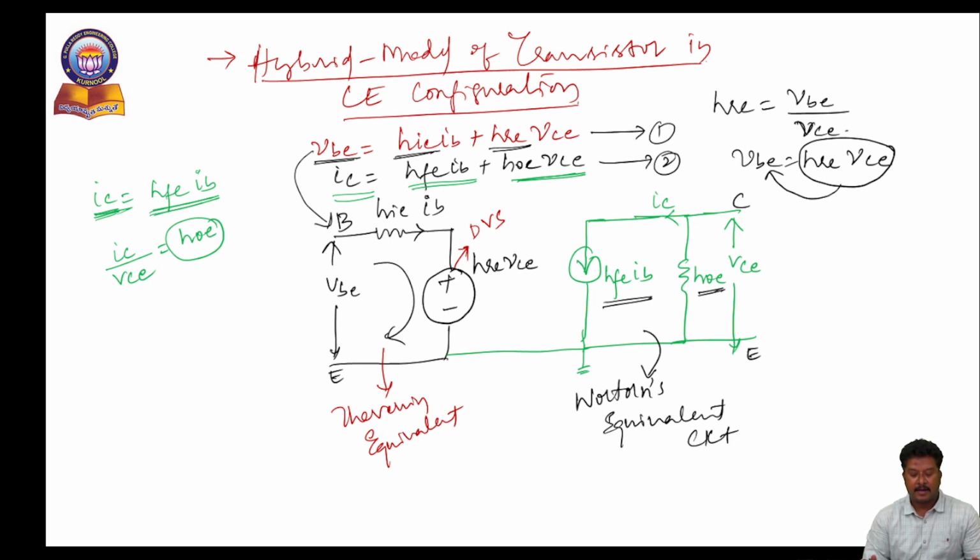Anyway, indirectly I am trying to frame the model with dependent voltage and dependent current sources along with linear elements. Unless we consider the internal behavior of a transistor as a linear element, it is not possible to find out which parameters influence the parameters of the amplifier. Then only can we easily design, control, and modify the internal structure of that amplifier.